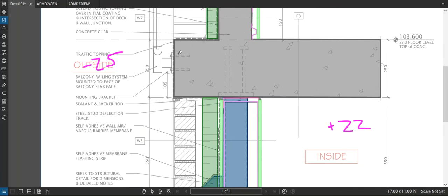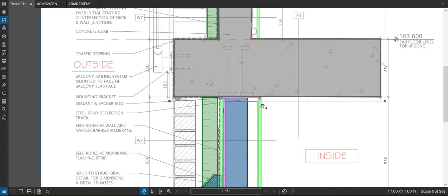Very, very likely, I would say, in this case, that condensation would start to form on the concrete right there, because that would be cold enough, probably, because of this thermal bridge through there. I would say there would probably be condensation happening right there in that concrete. I'd love to get in this building and see, but I'm quite confident of that, especially for prolonged cold snaps where it's cold outside for a long time. And so that's not good.